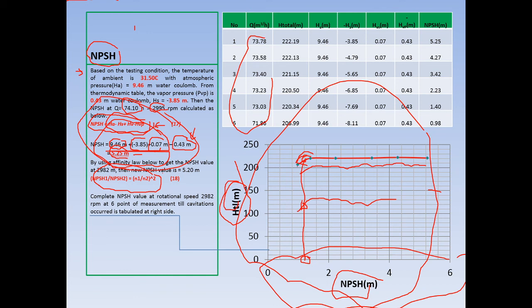Okay, when the cavitation starts to occur, that will be your NPSH required. Again, to repeat, NPSH required is a condition when you test the pump